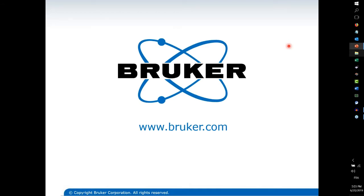Here, the 3 nanometer lateral resolution is actually the spacing between two adjacent digitalized data points. It does not represent reality, in which a 2 micron stylus will not see details below 1 micron.